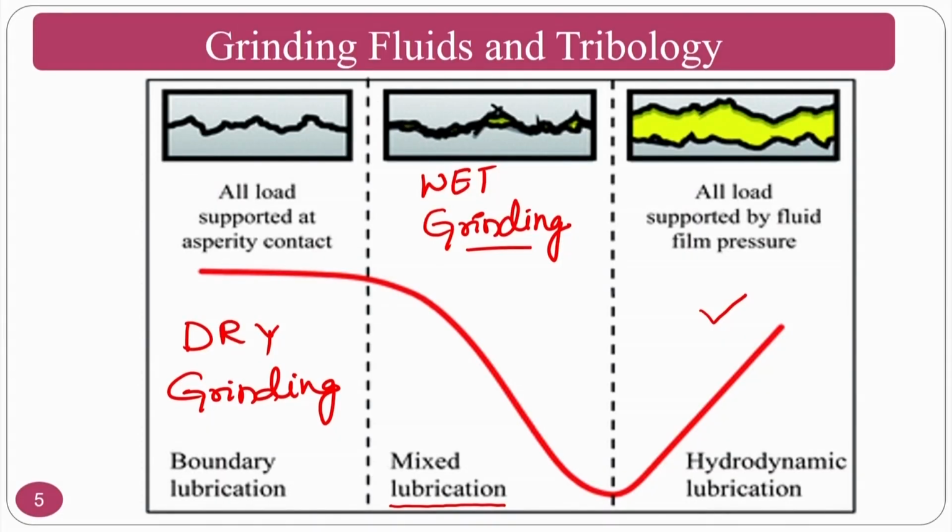But for our condition, I strongly suggest you to go ahead with wet grinding. You have seen in the previous slide, in the dry grinding, the spark is enormous, and in the wet grinding, you can avoid it by having a micro layer or a nano layer of cutting fluid.